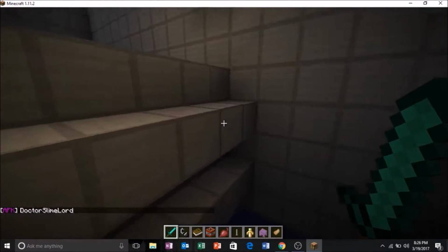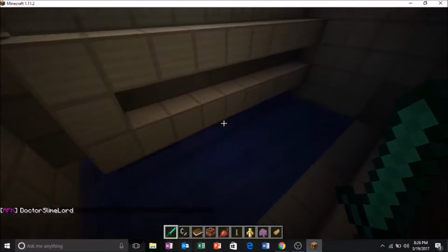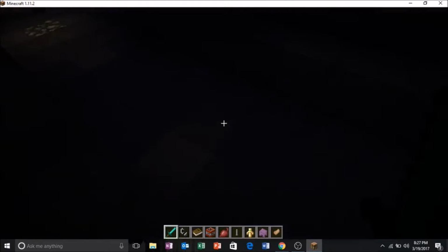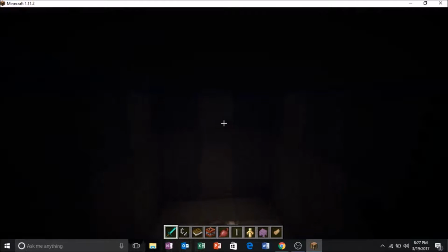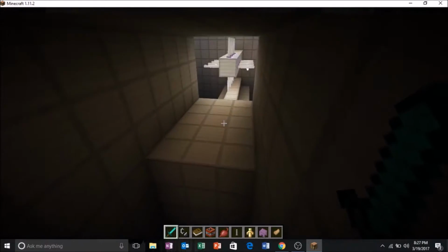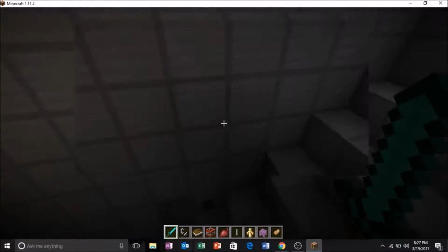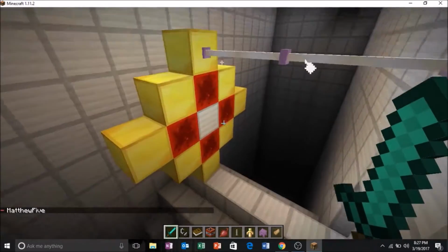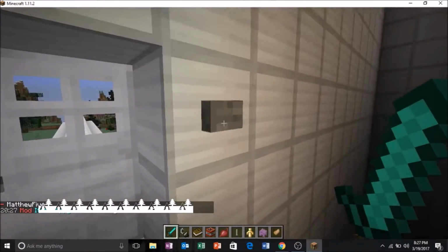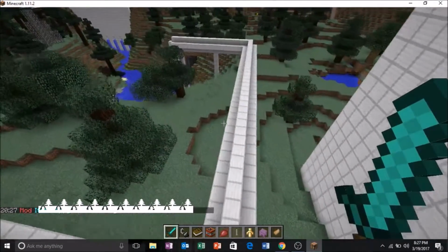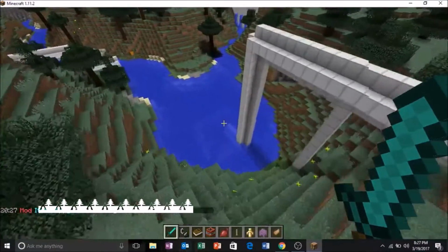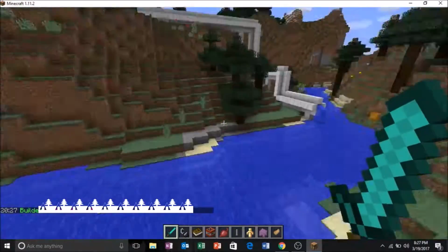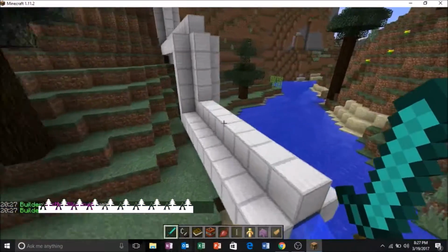Then the water vapor runs through a condenser, which pumps in cold water to condense the water vapors. This water vapor is then turned into liquid water and is reused to create more power. Here is the generator, which produces the electricity. And here are the pipes for the condensers. Cold water is brought in from a source such as a river, and hot water is pumped out.